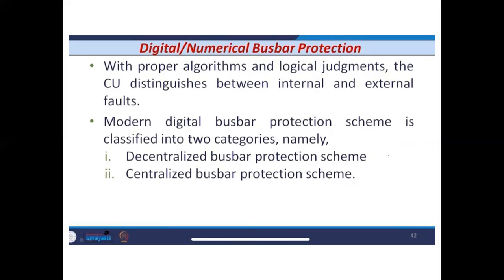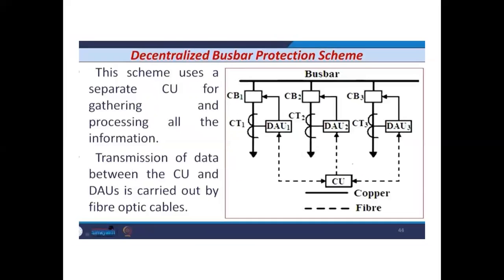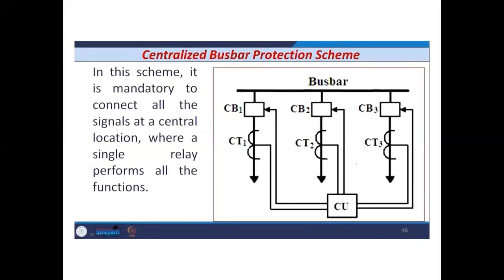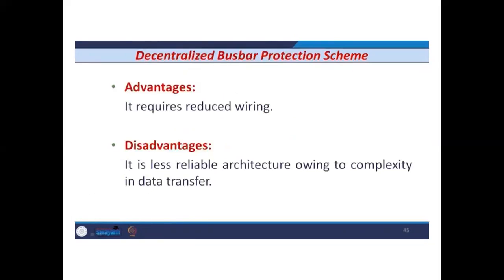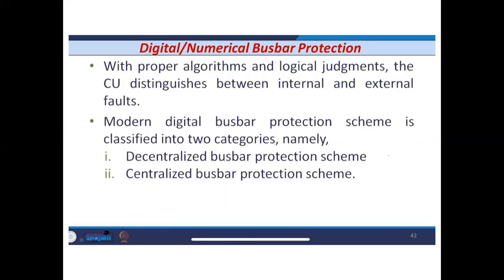Whether you have a separate unit for each line or feeder, or you use a common centralized unit, that is how the decentralized and centralized bus bar protection schemes are different. Let's see what the decentralized bus bar protection scheme is.